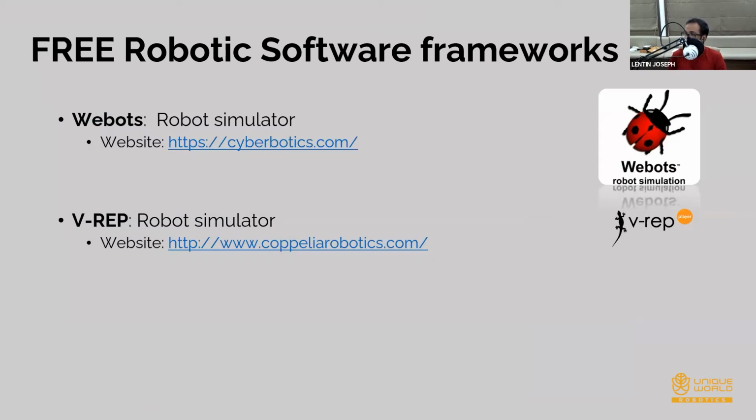What we have to provide is the mass, inertia, collision, friction, damping, all this stuff. Then the kinematics, the links and joints. All the things that are inside a robot, you have to put this information in the simulator itself, the kinematics and dynamics. Then that will be simulated in the simulator.